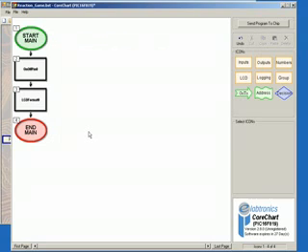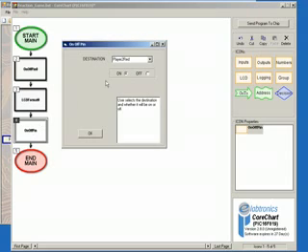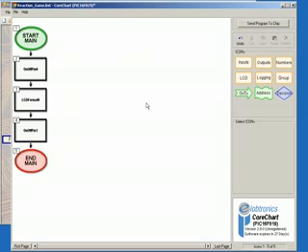Now we want to add another outputs, so we select outputs from the icons menu and then click on on-off pin and paste it by clicking the black arrow below icon 3. Double click on the icon to bring up its options and select Speaker in the destination field and then Off, and then click OK.